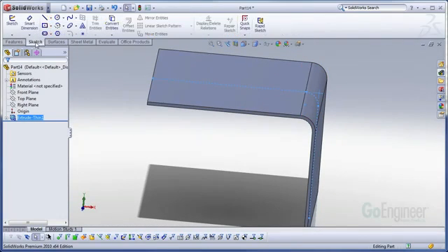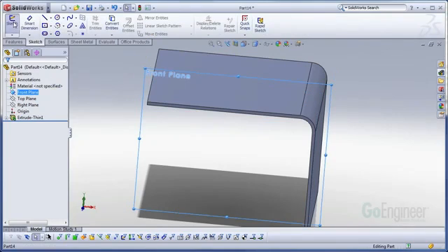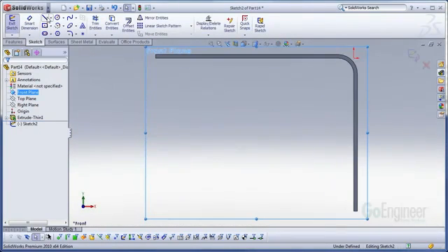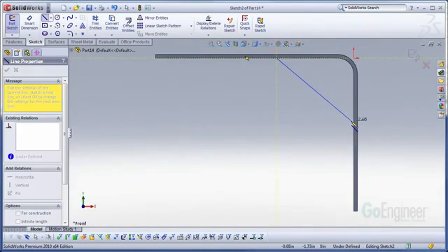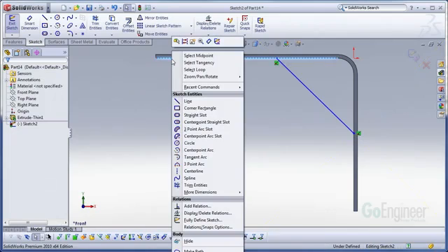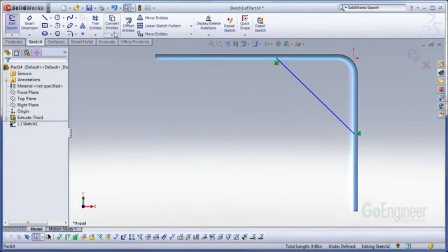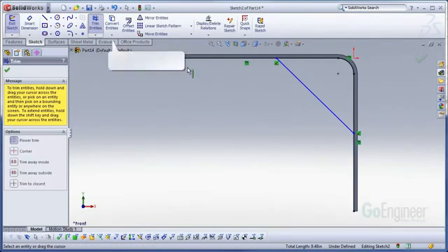Creating the actual forming tool, I'm just going to go back onto the front plane, create a new sketch, and put on whatever shape I feel like having for a forming tool. I just want diagonal in this case for my gusset. I'll get the back side of the profile here just by select tangency, convert entities, and then trim entities to trim off the excess entities.